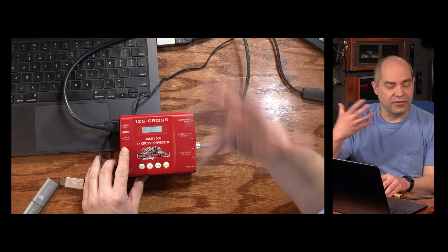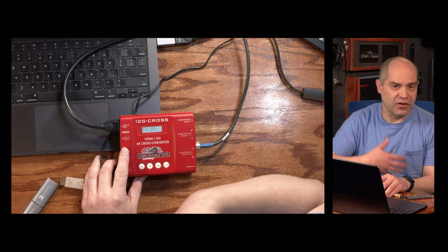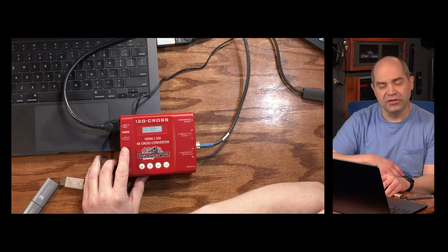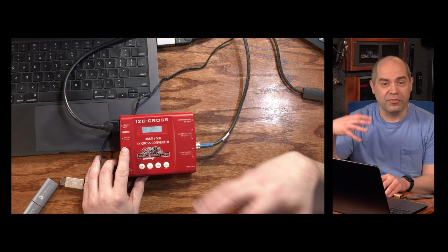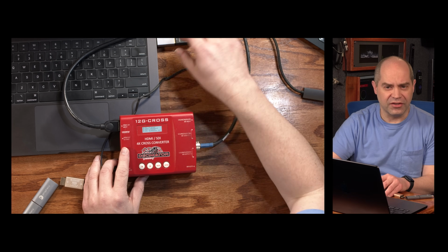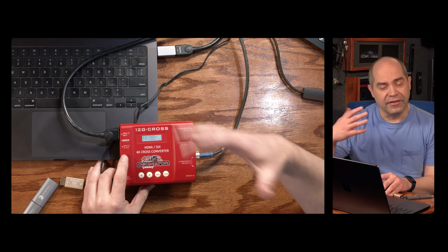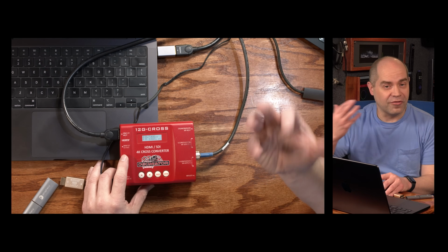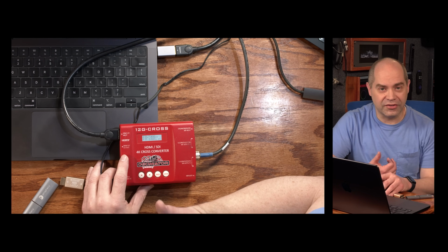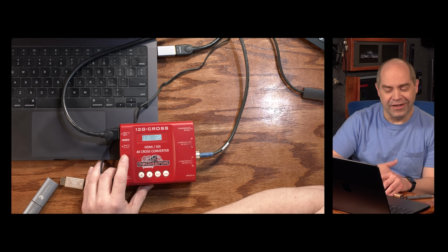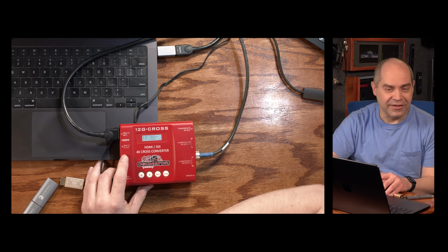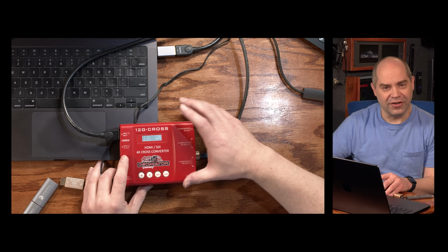So for example, if I wasn't running 4K on my switcher, I was running 1080p, and I needed to get the signal out of the computer to be 1080p, you can insert one of these things in the signal chain, and there you can see that at the top of your frame. That will basically tell the Mac the only signal format I know how to understand is 1080p 60 frames per second. So therefore the Mac does comply and gives you the resolution that you want.